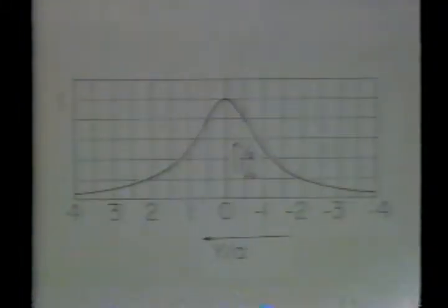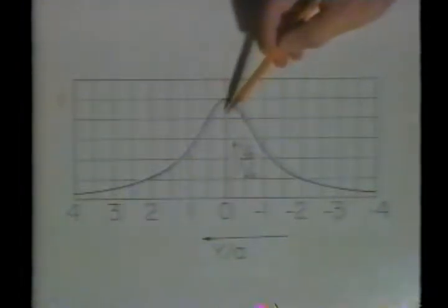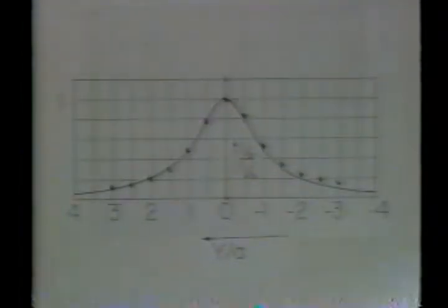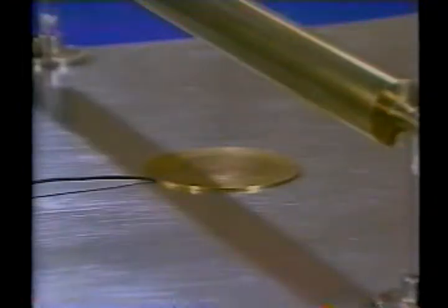In the analysis, it is assumed that the plane is grounded. Presumably, even the section of surface occupied by the probe is constrained to zero potential. In computing the current to the probe using this assumption, and then finding the probe voltage, we are making an approximation that is valid only if the voltage is small. One way to ensure this is to make the resistance of the scope small. The scope resistance is 1 megohm. It may come as a surprise that such a resistance is treated here as a short circuit. However, at 100 Hertz, the voltage is small enough.